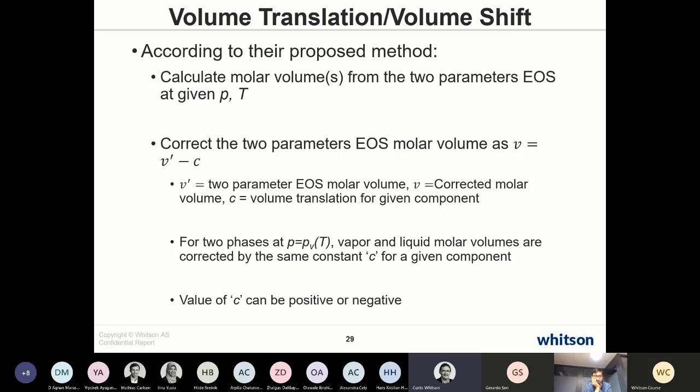When I put it in and ran all of these 15 cases in my original paper and used the C7 plus characterization methods that you were recommending with the volume shift and the specific gravity, molecular weight, and so on, basically using these methods that were available but he hadn't implemented earlier.